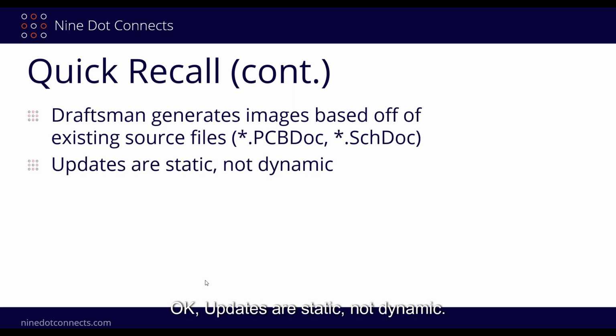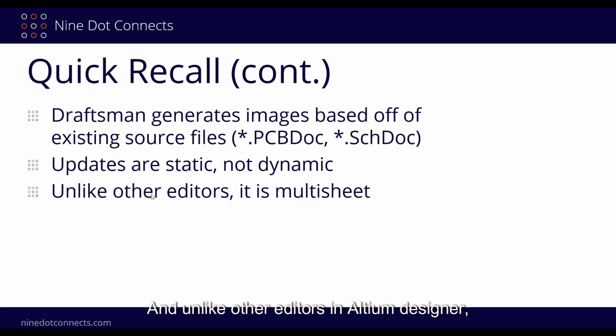Okay, updates are static, not dynamic. That's how Altium has always worked, especially with its libraries. And that's a good thing because you might change something and not realize that it had an impact somewhere else. So Altium expects you to say, yes, I made this change, update this, okay? And unlike other editors, in Altium Designer, it is a multi-sheet editor. So if you think about the PCB doc, the schematic docs, even the library doc, the editors, right?